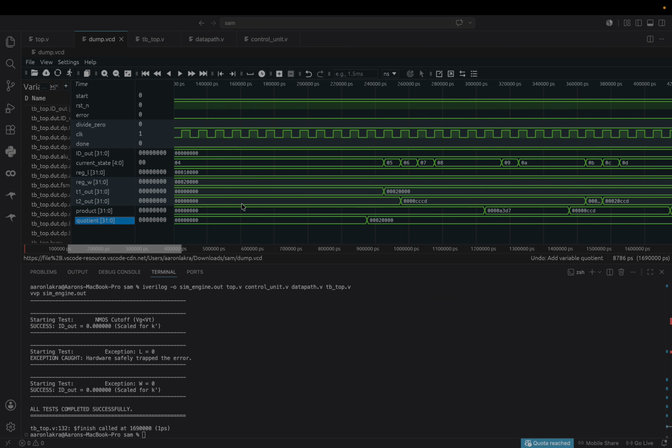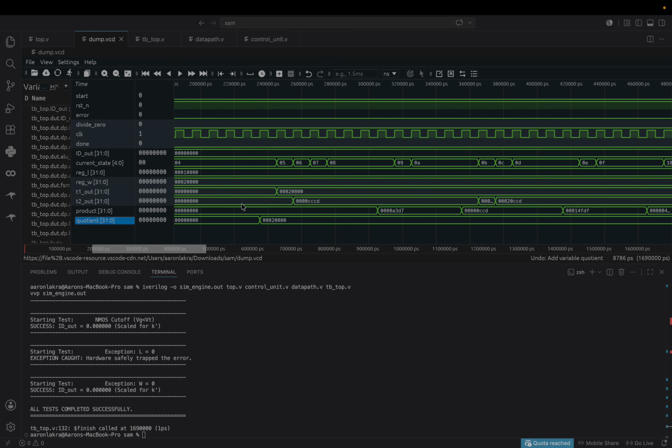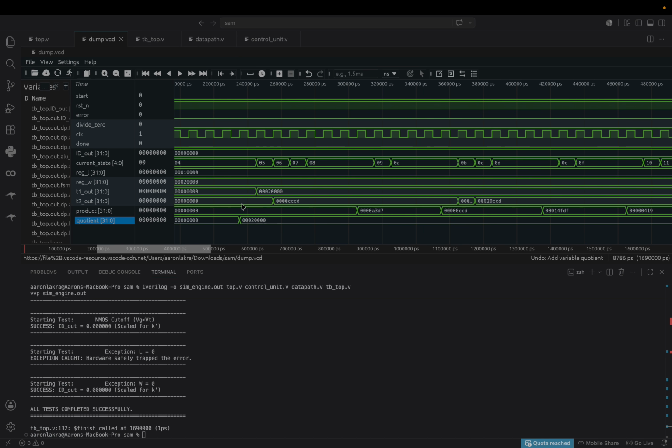As we can see, the simulation goes accordingly, depending on what values we give for the current equation, like what voltage values we set, for example the threshold value, and what length or width we give for our NMOS or PMOS transistor. If it is an NMOS transistor, it will use a specific formula, and if it's a PMOS, it will use a specific formula according to our design.